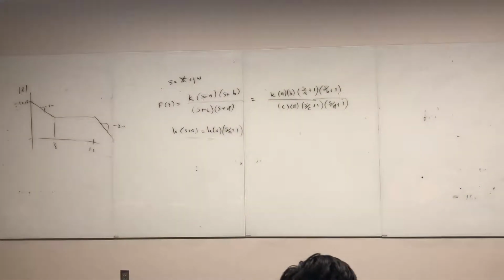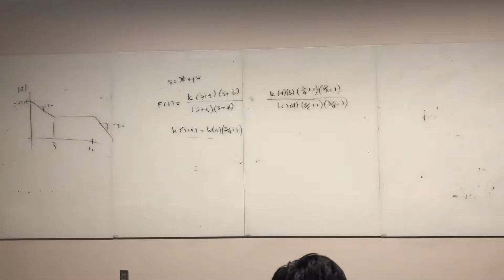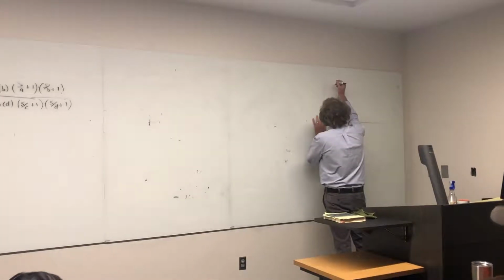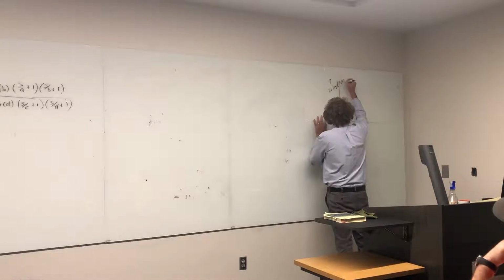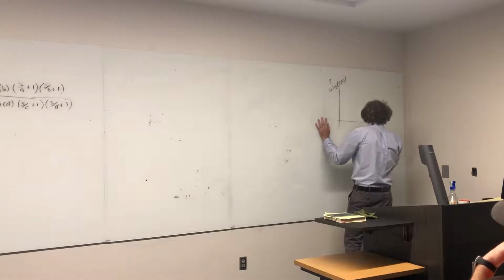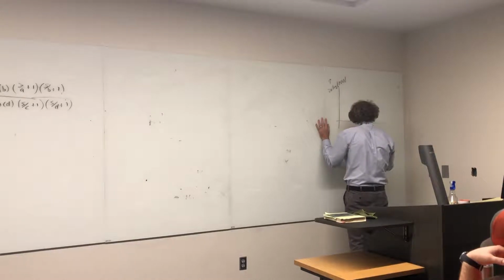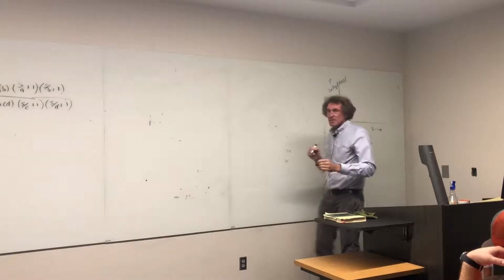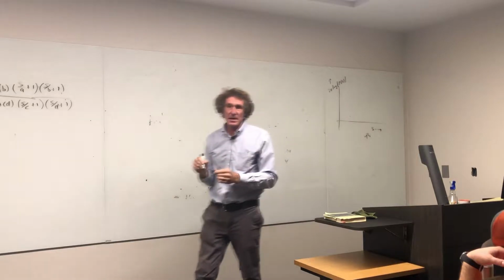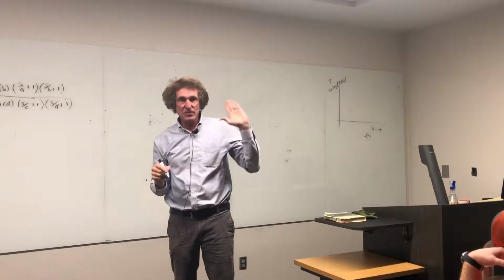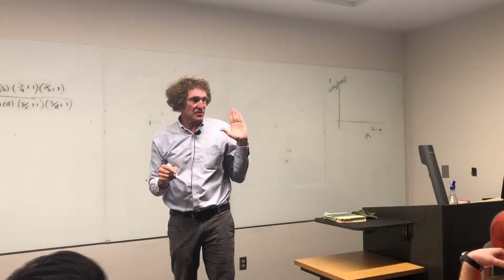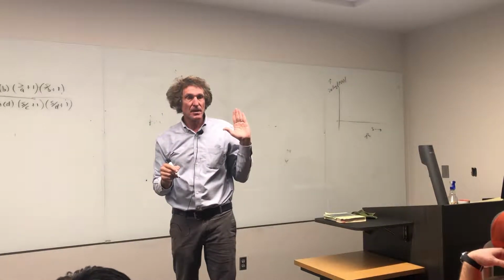Now, with a Bode plot, you've got to remember the scale on this thing. This is common. Since we're doing voltage, current, or things related to voltage or current, this will be 20 times the log of the magnitude of whatever the function is. On here, it's going to be s, but really it's going to be j omega, because s is j omega. He uses p in that. In signals and systems, we use just s. We did not make s equal to j omega. Do you all remember this class when you did this?